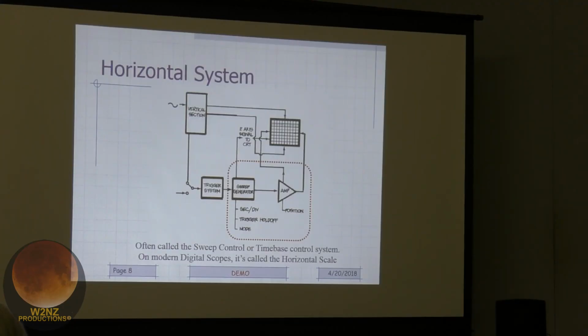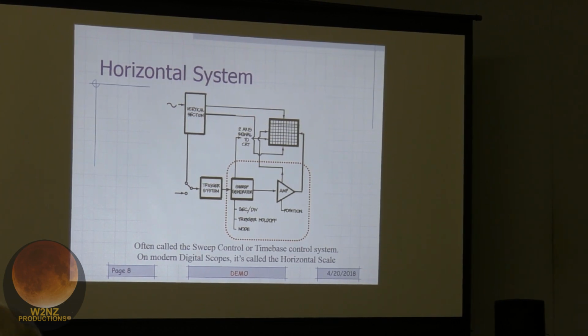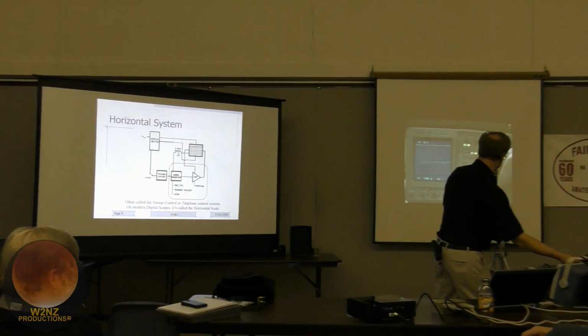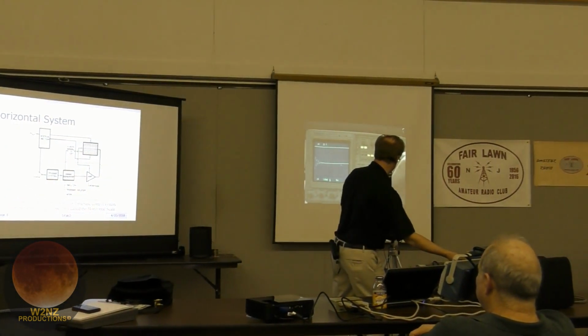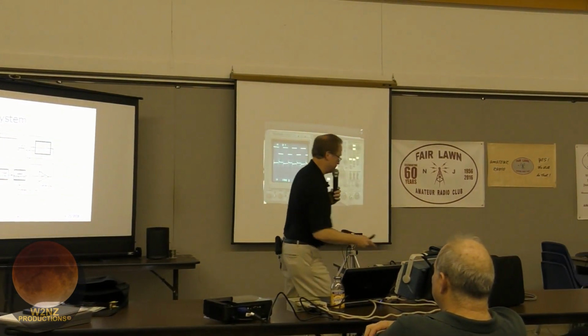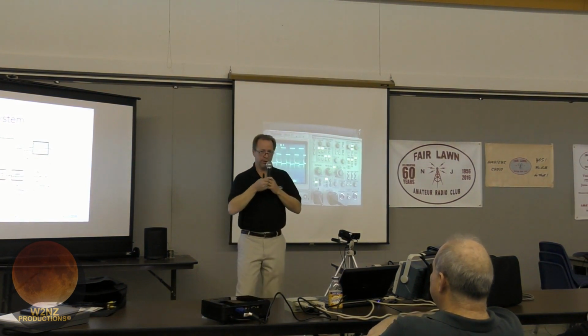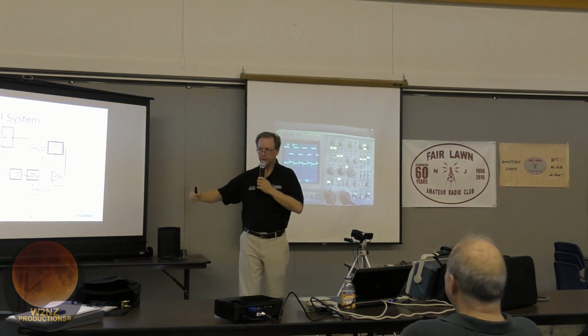I just changed my, you can see it says seconds per division right here by the knob. And if we speed it up, we can actually start zooming in and see the ringing that's going on right on top of that power supply voltage. And all we're doing is moving that beam faster, so we're stretching that waveform out so you can see those details.